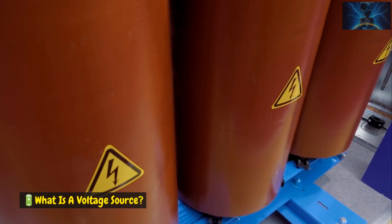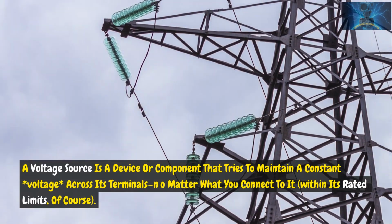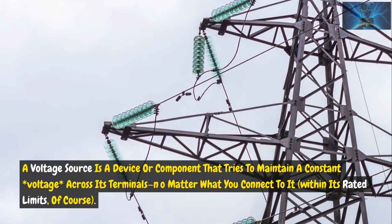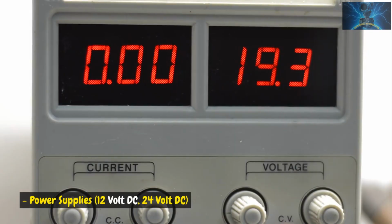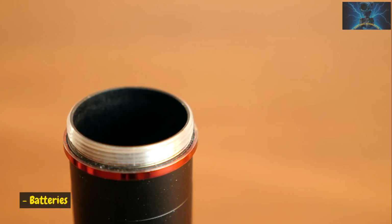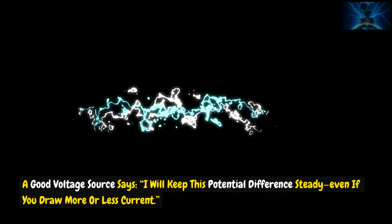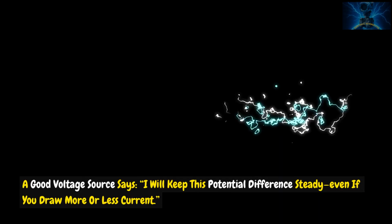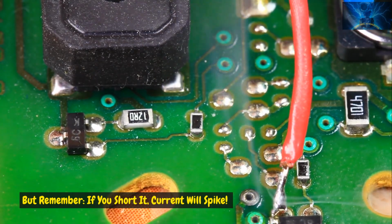What is a voltage source? A voltage source is a device or component that tries to maintain a constant voltage across its terminals, no matter what you connect to it, within its rated limits, of course. Examples: power supplies, 12-volt DC, 24-volt DC, batteries, benchtop lab supplies. A good voltage source says, I will keep this potential difference steady, even if you draw more or less current. But remember, if you short it, current will spike.